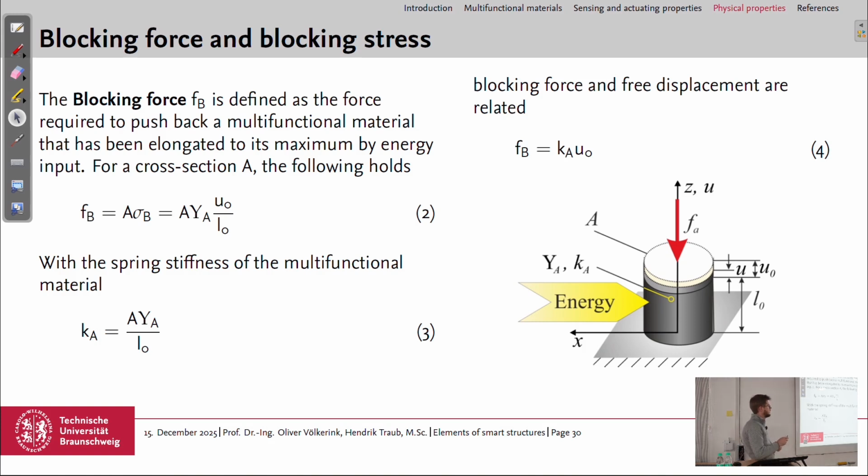Material, neutral one. In our basic principles here, we also only have the piezoceramic material. So from the idea, if you just have a block of the piezoelectric material and maybe some electrodes to apply the electric field, then in the first step, you will measure the free displacement, just applying a maximum electric field and see how it extends, and measure this U0.